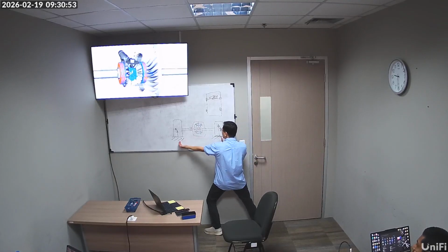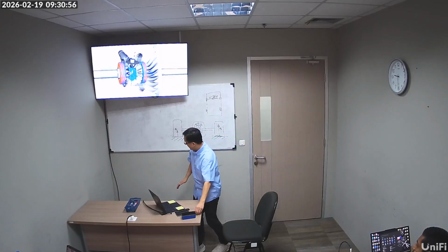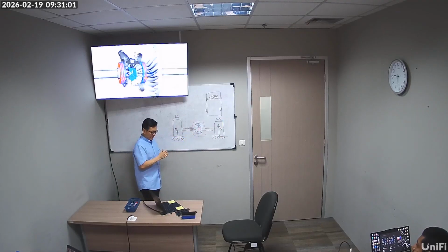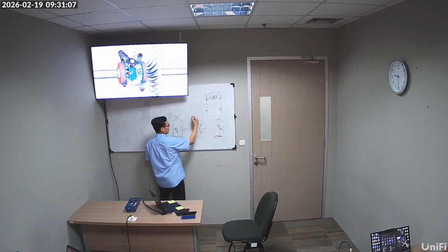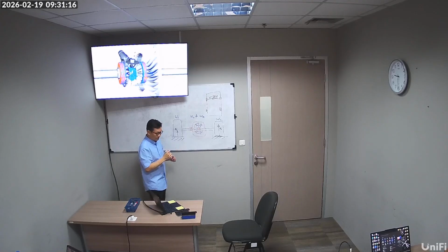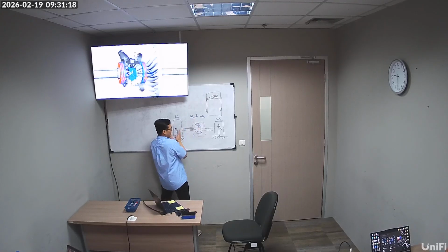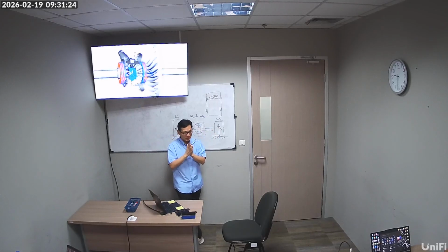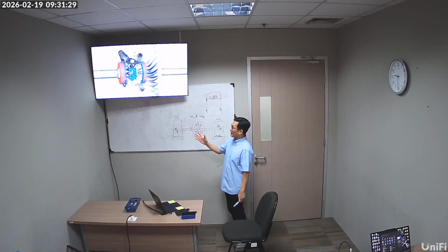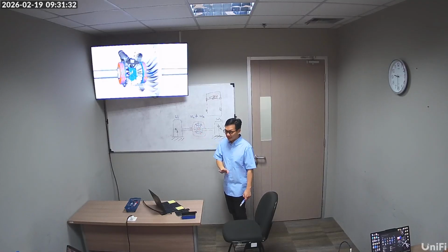Yes, when it slips, but to be precise, when does the clutch pack have relative motion? When the RPM of the left wheel is not equal to the right wheel, then there is some slippage, right? Otherwise, they just move together, no problem. So the clutch pack is not even used most of the time when you're going straight.